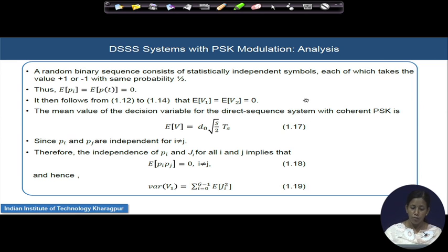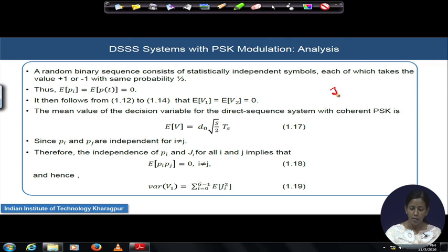Now, we have to look inside the other part on the left, where V 1 is. V 1 is the jamming section, but in order to understand the power contributed from the jamming section, we have to understand that the jamming is not standing alone here. In the receiver, the jamming signal is already spread by the spreading sequence p(t), so its spectrum is getting dominated by the spreading signal. The property of this p(t) we now have to look into.